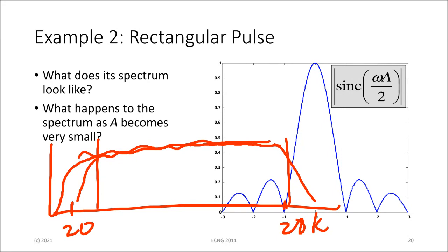Again, a pulse has a known frequency signature. If the cable is working well, then at the other end, 1.5 miles down the road, a piece of equipment will pick up the transmitted pulse and compare the spectrum of the pulse to what was known to be sent in. If there's too much of a deviation, we know that there's something wrong with the cable.